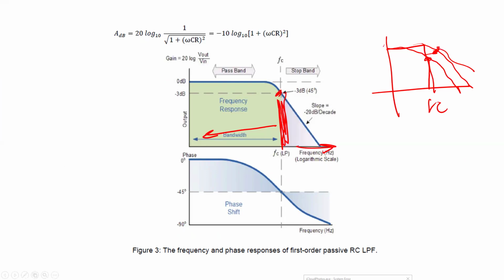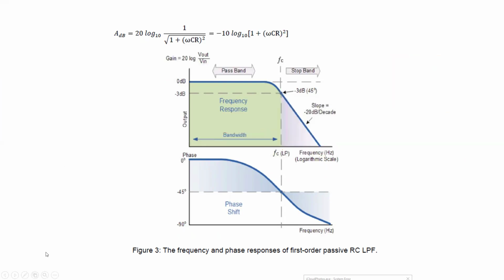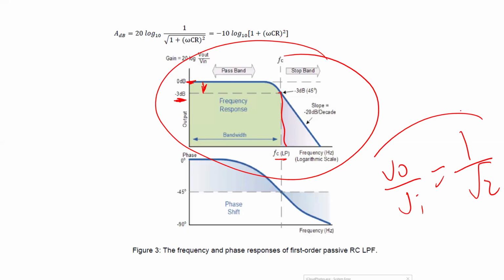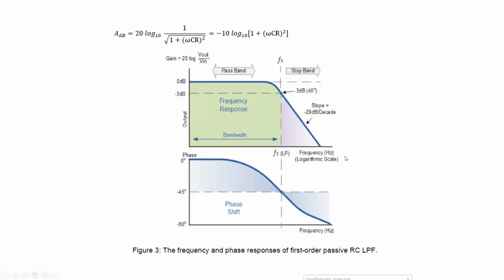Okay. So how can we measure this cutoff frequency? Number one, most of the time we are going to use decibel or logarithmic numbers. If we are doing that, see what value here, and when it drops by minus 3 decibel, the corresponding frequency here is the cutoff frequency. Same thing if we do measurement in the coming lab: when you find V output divided by V input equal to 1 over square root of 2, this is the cutoff frequency as well. Okay. This is what we call frequency response.